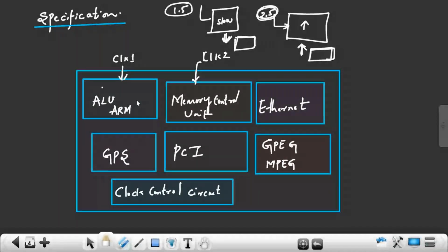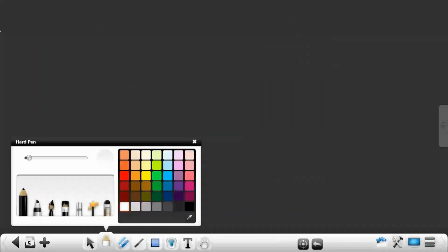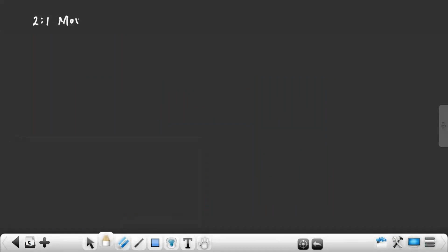Yes, almost correct. See, for any circuit, it is very difficult to represent it through its structure, rather we can describe it through its behavior. See, everyone has written a truth table, correct? What is a truth table? A truth table is nothing but the behavior of the circuit, how the circuit is behaving. So if I tell you to write the truth table of a mux, I will give you a 2:1 mux, right? This is a 2:1 mux or a D flip flop, right?